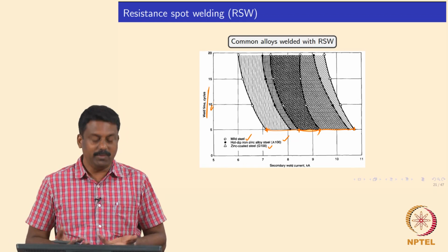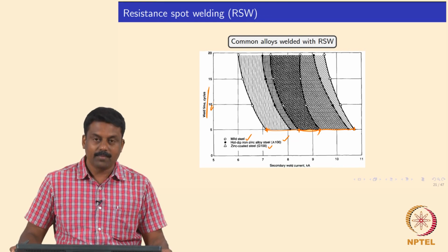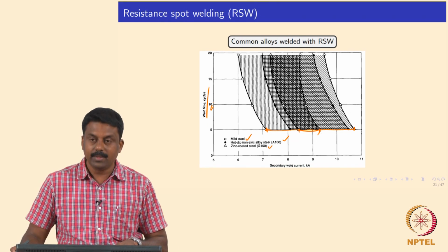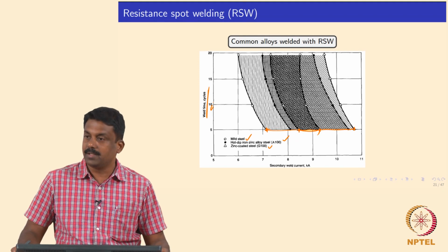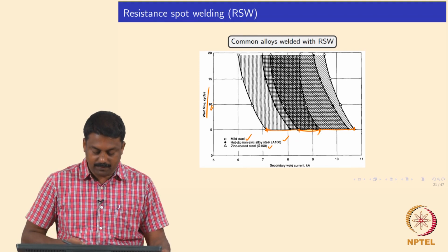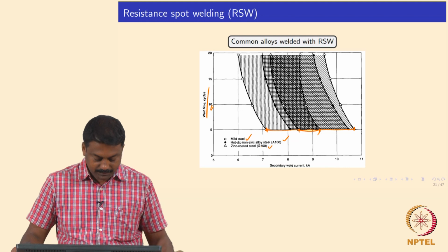The weld growth curve I am showing here is a function of current and time. So we can also generate the window in which you can operate for a given composition and thickness.